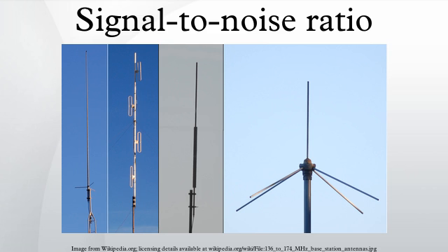Measuring signal-to-noise ratios requires the selection of a representative or reference signal. In audio engineering, the reference signal is usually a sine wave at a standardized nominal or alignment level, such as 1 kHz at +4 dBu. SNR is usually taken to indicate an average signal-to-noise ratio, as it is possible that instantaneous signal-to-noise ratios will be considerably different. The concept can be understood as normalizing the noise level to 1 and measuring how far the signal stands out.